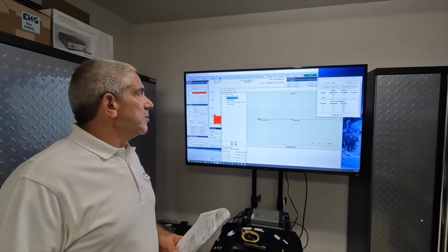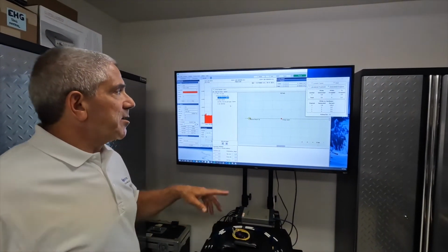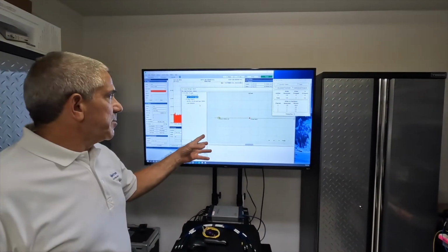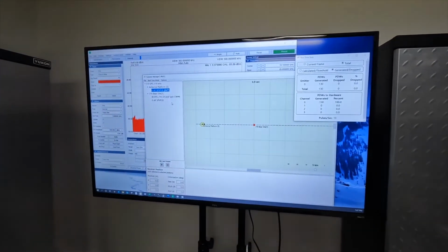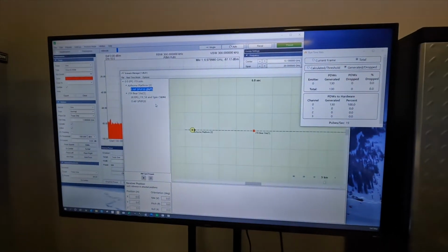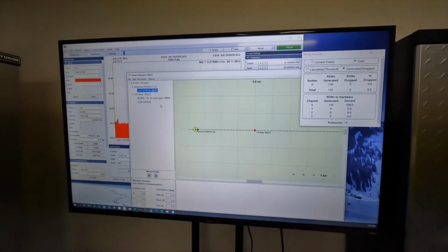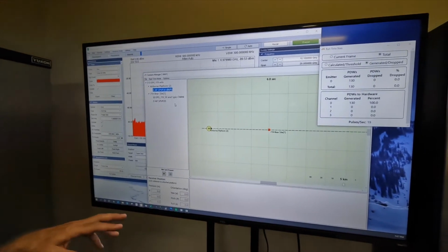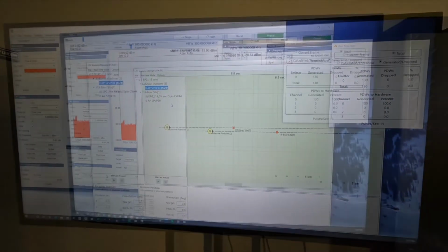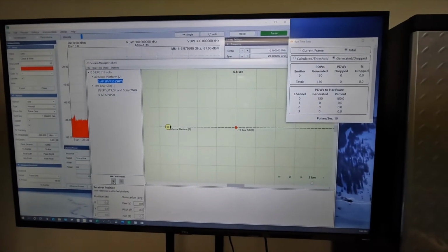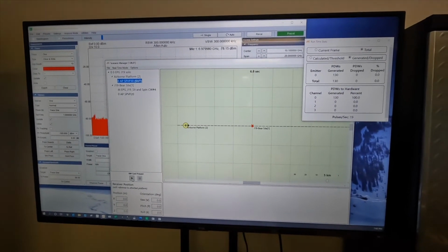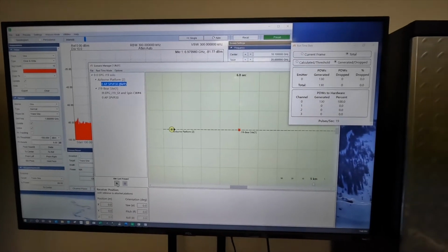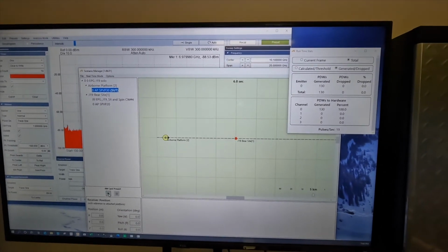All right, so without further ado, I'm going to execute the scenario, and then I'm going to point to the runtime statistics window. And what you're going to see with this emitter is planned for a 120 degree per second circular scan rate. So what that means is once every 3 seconds, its directional antenna will be sweeping through the system under test receiver. Okay, so when we execute this scenario, the airborne platform will start its run inbound to the fixed ground platform, doing a circular scan at a 3 second sweep rate.